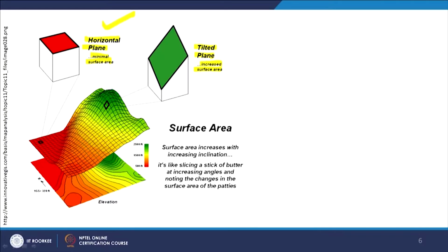But if by mistake somebody does the calculation only using the horizontal plane, then basically he is underestimating. And I tell you, I know various projects which have failed because people underestimated the earthwork, for example. Using just the planimetric concept and assuming everything is flat, like using survey toposheets, they calculated the length and area and grossly underestimated the work, and later on such projects go into real trouble. So nowadays it should not be done in that way.